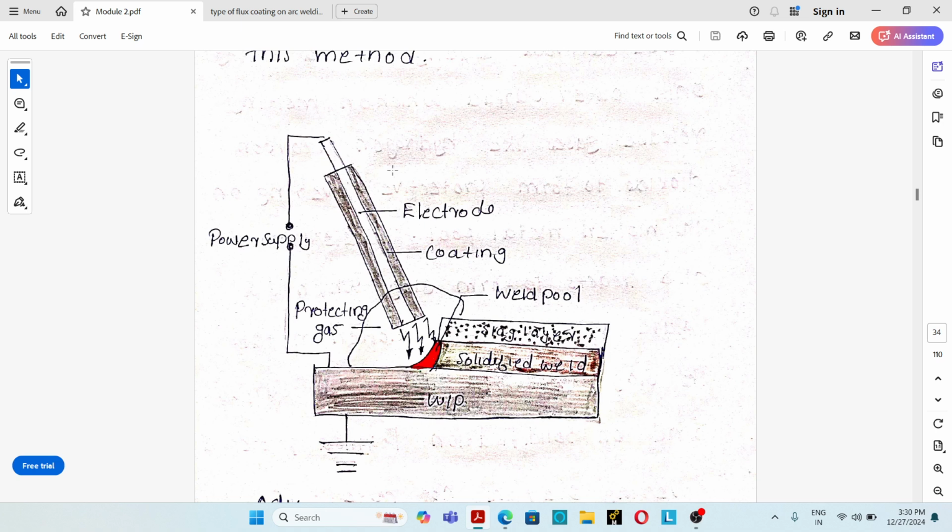In the shielded metal arc welding process, the main parts are a welding machine, an electrode holder, a ground clamp and a welding cable. The welding machine is a DC or AC source. The electrode holder is connected to the electrode and is used to hold it. The ground clamp is connected to the base metal to be jointed. Power sources are an AC welding transformer, DC motor generator, rectifier or inverter, which are also used as power sources in the SMAW process.